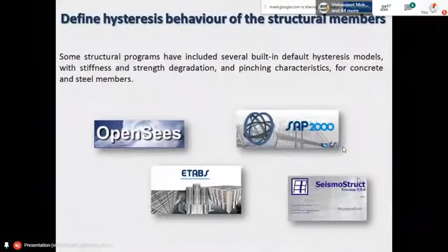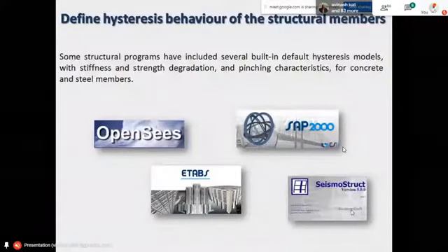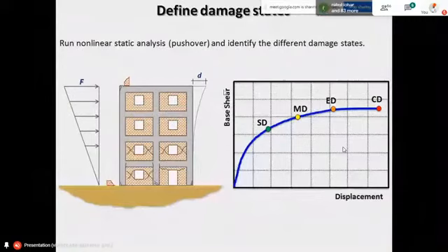SeismoStruct is also there. SeismoStruct is a software in which incremental analysis is inbuilt, just like pushover analysis is inbuilt in the SAP library. Similarly, if you want to perform an incremental dynamic analysis, go for this particular software, because there it is inbuilt. Then after getting a capacity curve, maybe from a pushover analysis or from an incremental dynamic analysis,